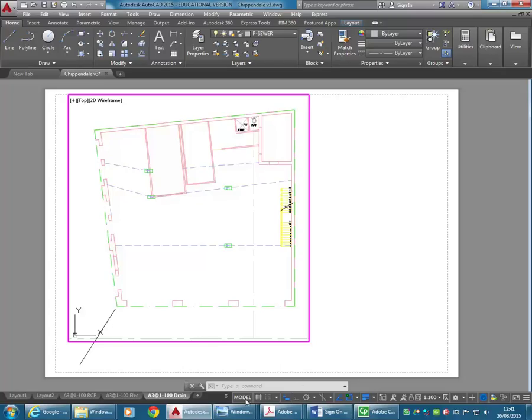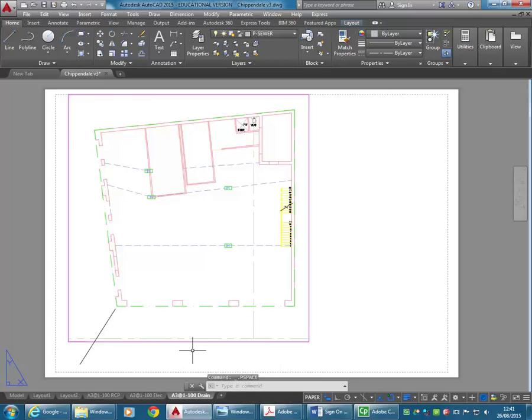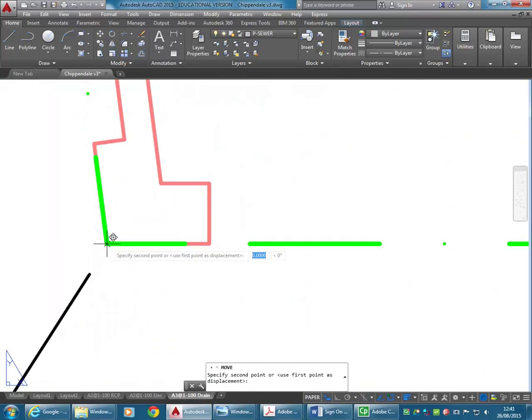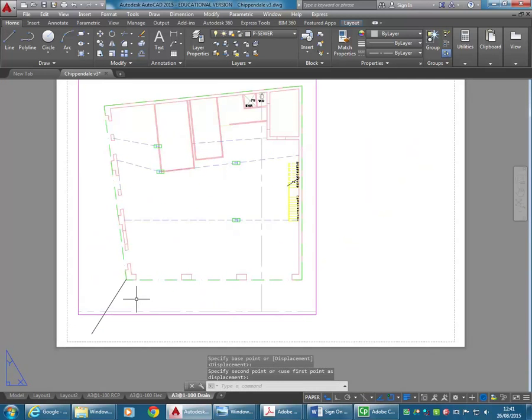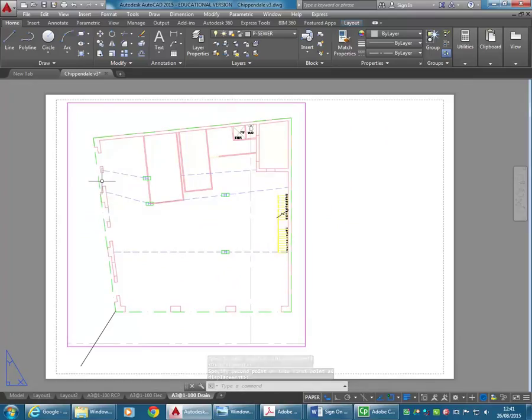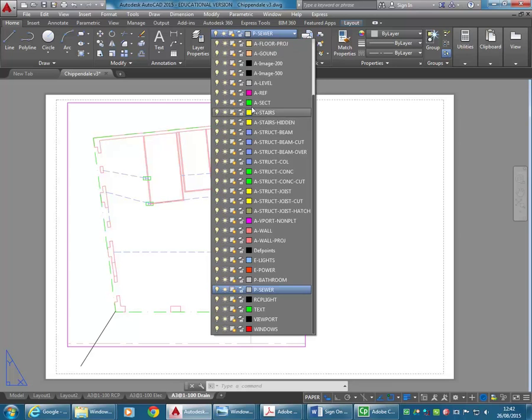So I'm going to go back to paper space. And I've got to move the whole viewport now on the page. So I'm going to select that border, which is the viewport. Click move. Zooming in, I can snap to that corner and then snap it onto the end of the line. So I've got the plan in the same place, and that's really half the battle. But it doesn't hurt to get that viewport back to the original size, because remember, I've moved that viewport border slightly. So that's why I drew the rectangle.